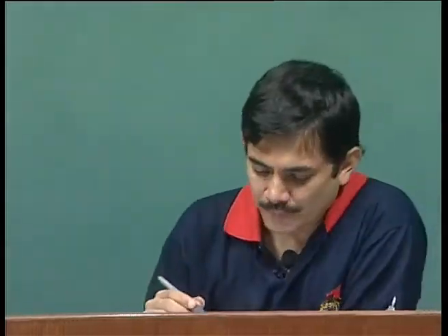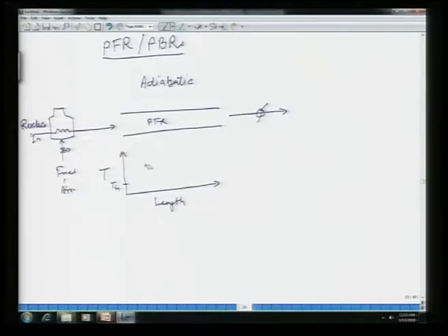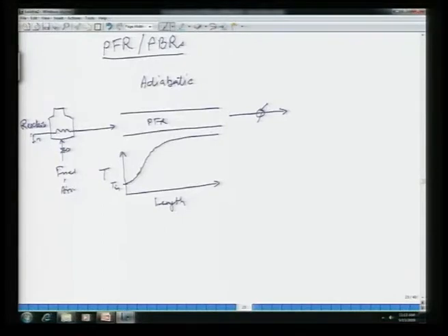Okay. So, what will happen is, initially I have not drawn it properly. Initially the reaction rate will be high, the rise in temperature would be high, you will have this exponential kickoff in reaction. Then, because of depletion in the reactants, the amount of heat released will start to go down. So, the rate of temperature rise will go down, and ultimately all of the reactants would have reacted, conversion is complete, therefore, there is no reactant left to react, and so the temperature profile becomes flat. Does that make sense or no?